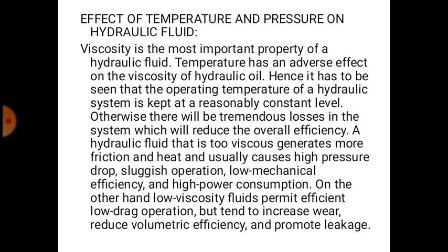A hydraulic fluid that is too viscous generates more friction and heat and usually causes high pressure drop, sluggish operation, low mechanical efficiency and higher power consumption. On the other hand, low viscosity fluids permit efficient low drag operation but tend to increase wear, reduce volumetric efficiency and promote leakages.